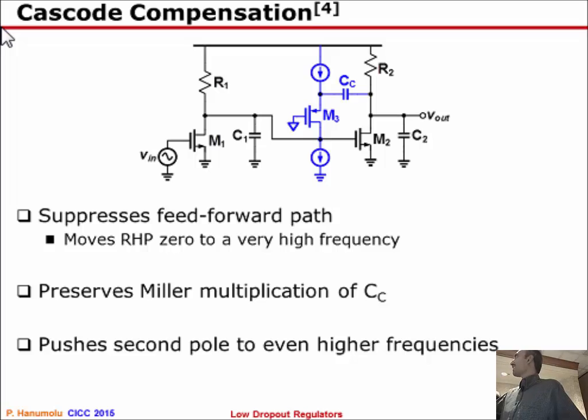So, what I'm saying is, if the question is, we need these additional current sources, my answer is you don't need this. You can think of this M3 being part of the cascode stage of the first stage, and you can merge string 1 and 3. M3 becomes the cascode for M1, and the current source becomes R1. Okay, thank you. Yeah, I'll hang around. You can come and talk to me. If I can draw stuff, it'll be easier.